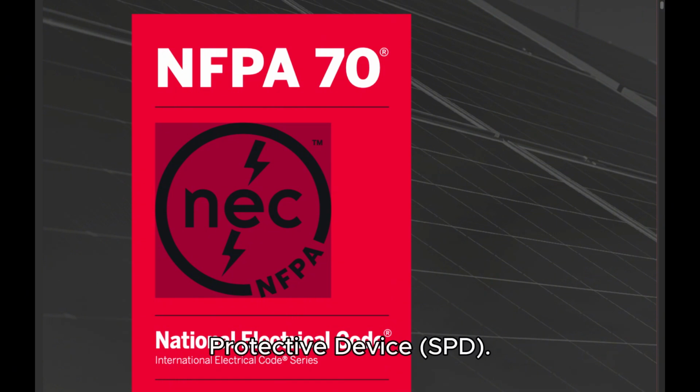CMP5 surge protective device, SPD. A protective device for limiting transient voltages by diverting or limiting surge current. It also prevents continued flow of follow current while remaining capable of repeating these functions, and is designated as follows. Type 1. Permanently connected SPDs intended for installation between the secondary of the service transformer and the line side of the service disconnect overcurrent device.